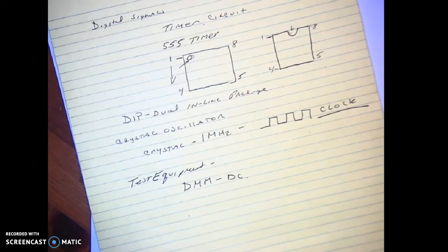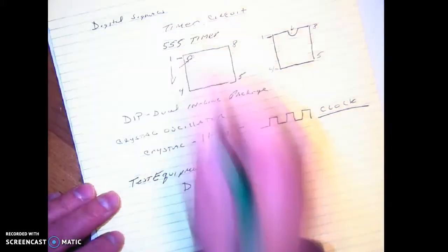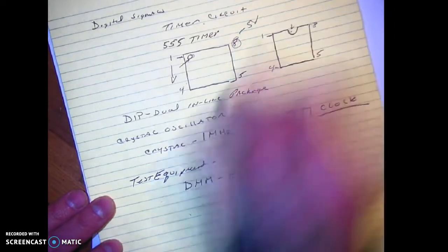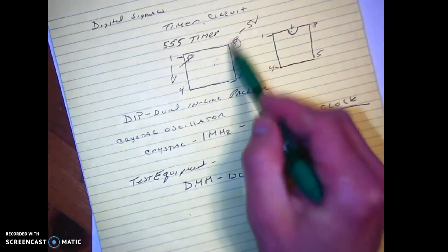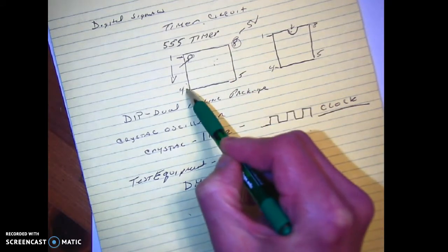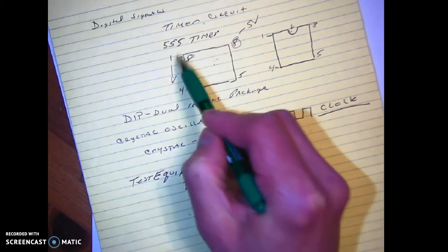The other piece of equipment is called a logic probe. A logic probe is basically a digital instrument that has a little point on it, and what you do is you hook it up to your 5 volts, and you touch it to one of these pins, and let's say you touch it to pin 8. We know that pin 8 is a 5 volt signal. Well, if this chip is not working, the first thing I want to check is whether I have voltage at the 5 volts, and I also want to see what happens to my ground. So, excuse me, ground right here.